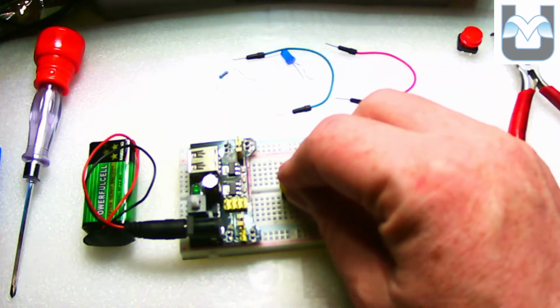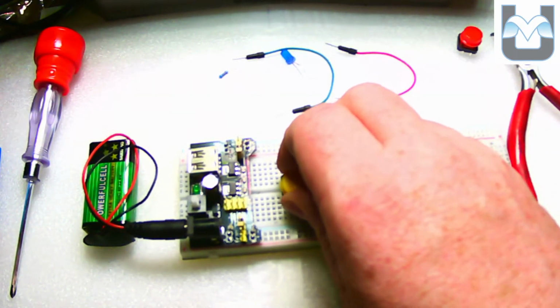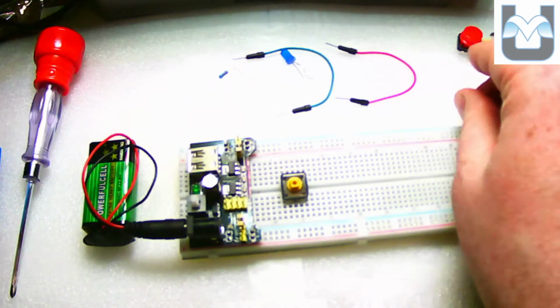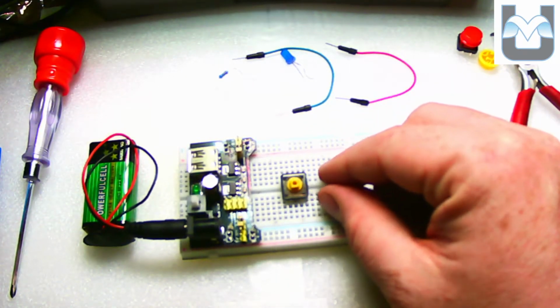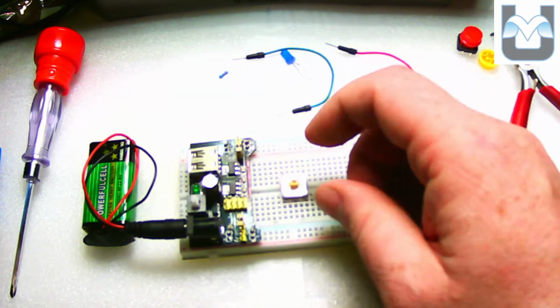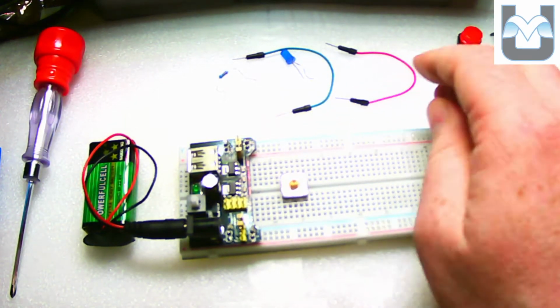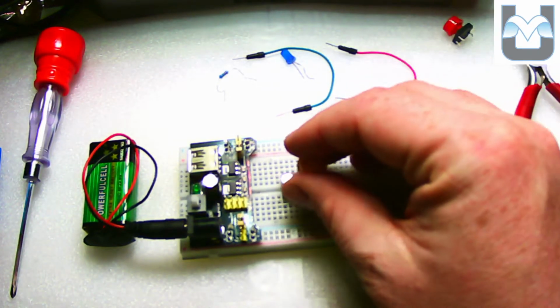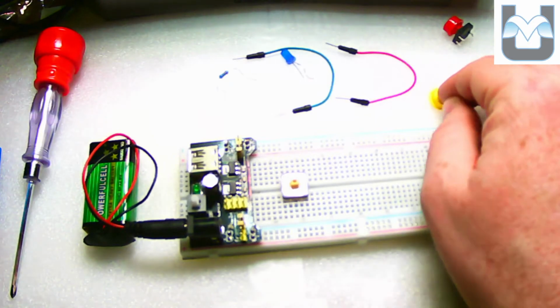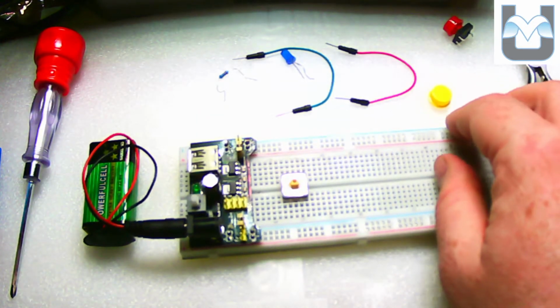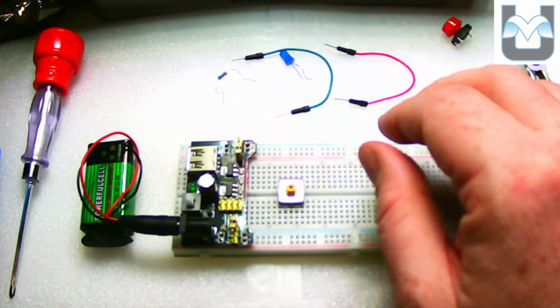I've already taken my push button and put it onto my board, the one that I'm going to use. I want to make note with these ones that are on the breadboard, you really need to push these into the breadboard to get them to stick. If they're not quite in the breadboard, the legs aren't actually touching metal, therefore there's no electrical connection. I'm going to leave the top off of this one for just a second while I hook up the circuit, but you're more than welcome to put it on there.